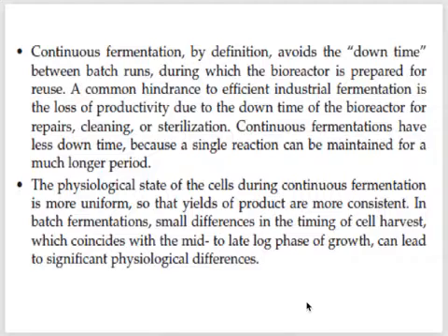In case of continuous fermentation, we can avoid the downtime between batch runs, which is longer in case of batch fermentation process. Because when we do fermentation using batch fermentation process, we do it batch-wise, right? First you run one batch fermentation, and after it is done, you have to harvest your products and clean and sterilize the bioreactor. That means you have to prepare it for the next batch. It requires some time. This time is called downtime.